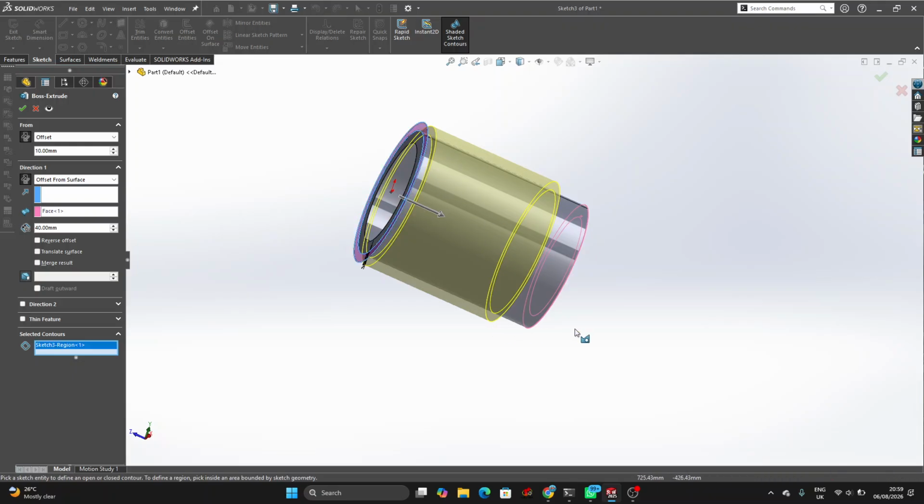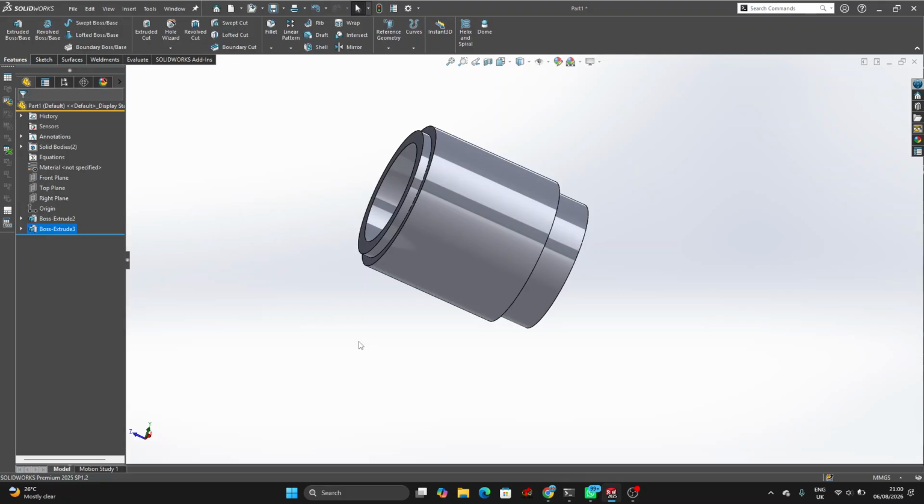And what the thin feature does is you can extrude a sketch that has an open loop, like it is not closed, which is otherwise not possible. I will show you that scenario too. So with this multi-body part now, I will use this ability to explain it. Can you see?